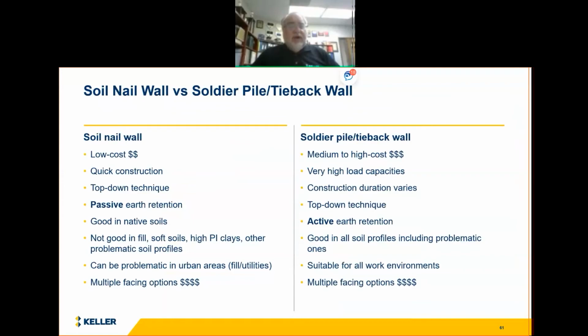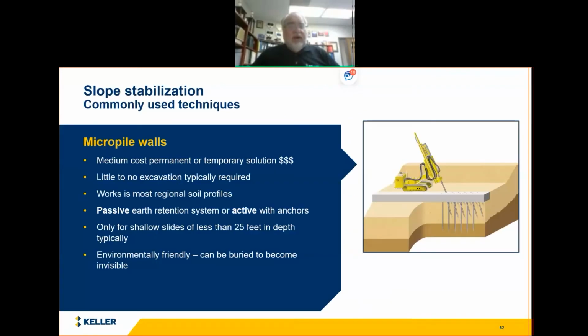Soil nailing has a few limitations: it doesn't work very well in soft fills, soft clays, etc., or in urban areas. So obviously you get more bang for the buck in many cases with the soldier pile tieback wall, but you're going to pay more for it. So they both work very well.